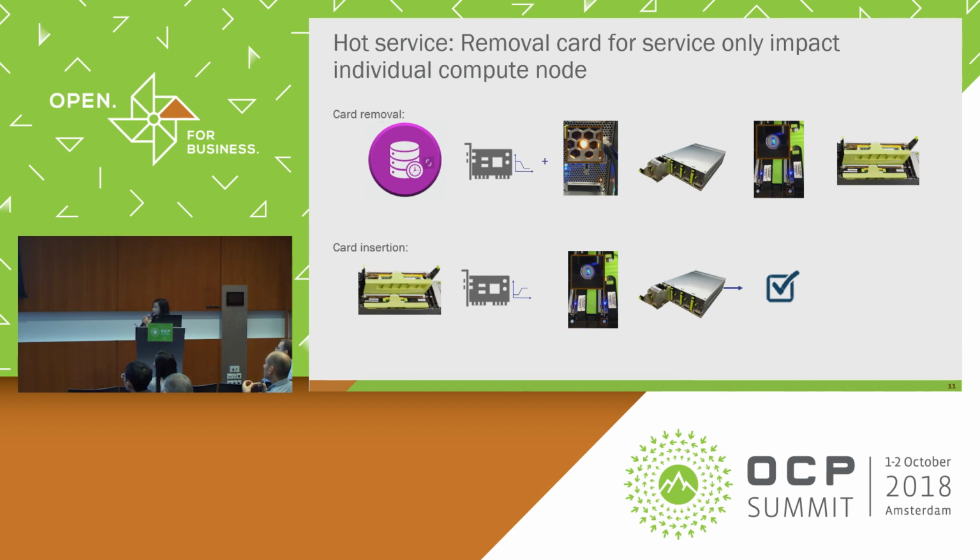Okay, and then we can turn on one of the LED indicators to show which slot needs service. So the LED will blink, and then you pull up the chassis, do the service, and put the new card back. In this case, the rest of the three Twin Lakes are still working. Then you do the card insertion, power on the slot, turn off the light, and put it back. The rest of the three are still working during all the services.